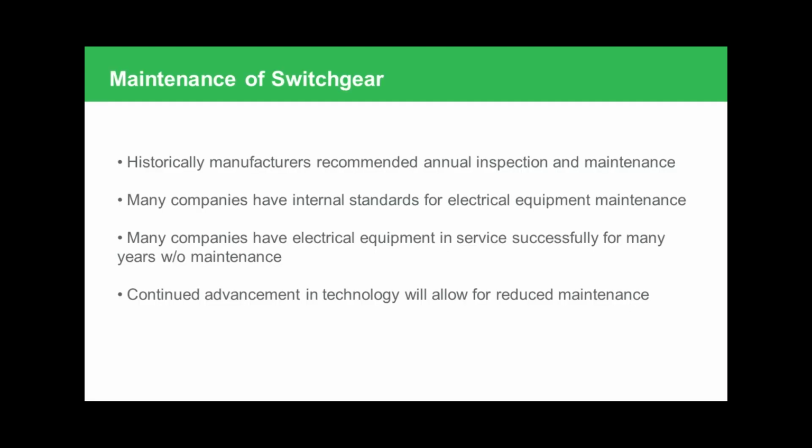Inspection and maintenance that you'll have with either switchgear. So historically, your maintenance on your withdrawable switchgear, of course, will be higher because you'll have more moving components. You'll have to maintain those with the lubricants. You'll have to do some spacing. You have the rear working aisle where you can get into the switchgear. So many manufacturers will have like an annual inspection of every year. They'll maintain their switchgear. Some companies don't have to have that standard based on what type of switchgear you have in place. So many companies have internal standards based on just equipment maintenance and protection that you'll need for your personnel.